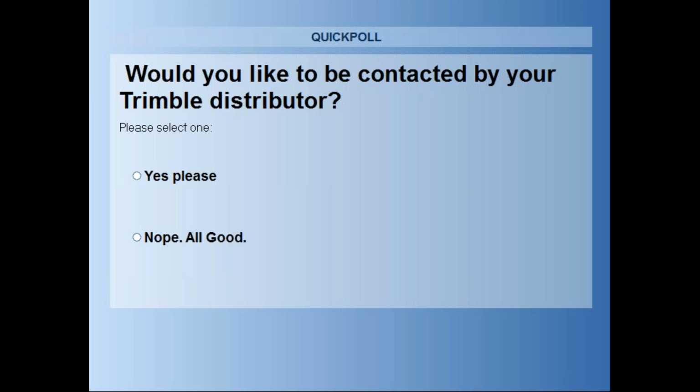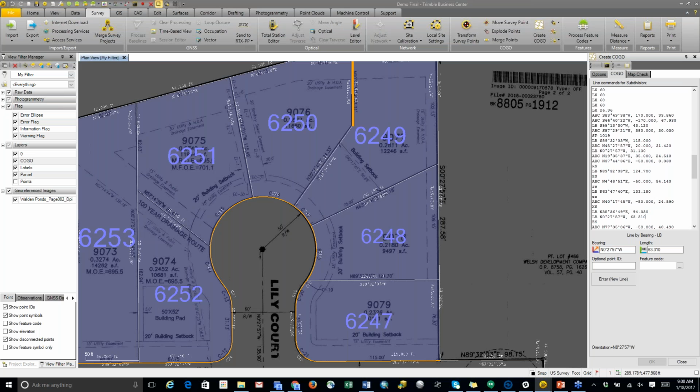One I did see, let's see if I can find it again, was in regards to using different units. The question was posed: if they're in the same area and one survey plan is in meters and azimuth and the other one's in feet and bearings, do I have to change my project settings, or can I use feet and bearings in a metric azimuth project? And the answer is you don't have to change your project settings. What you can do is enter, I believe it's FT. FT, yeah. So if you enter in a distance that's in feet, you enter FT after that distance.